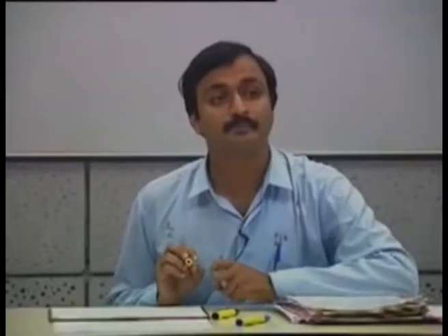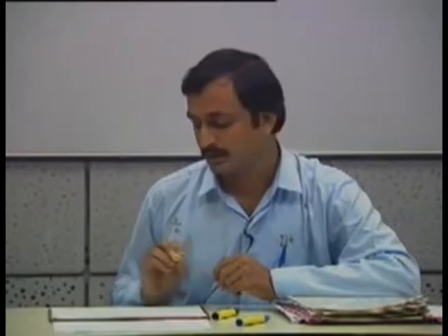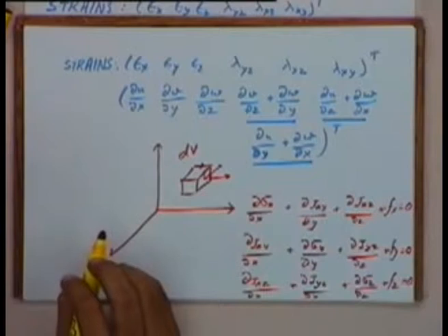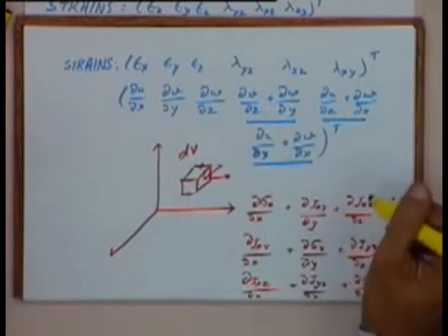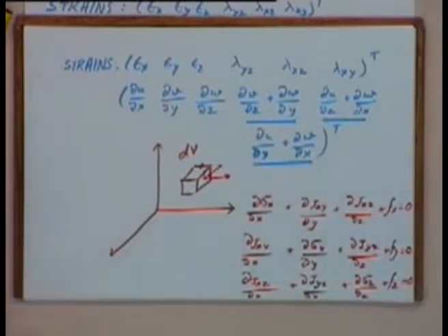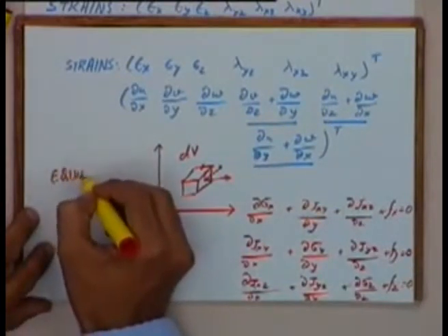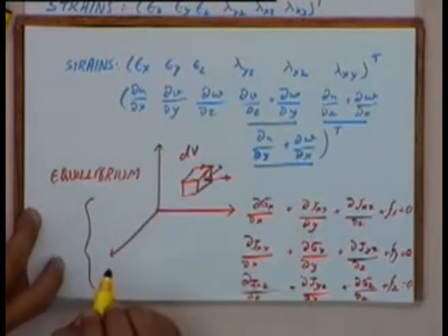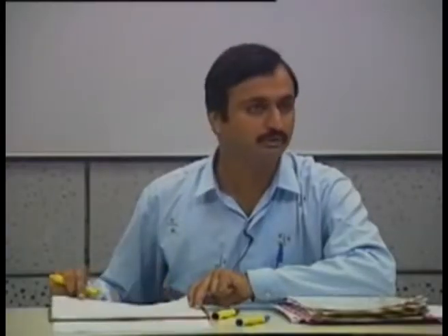Yeah. In all these equations, the force sign should be negative because the external force should be equal to the stresses. No, the signs will be taken care of by the direction that we are choosing. So the magnitude can be negative, but because of the sign convention we are choosing, we are getting a positive term. Okay, so there are 3 equations we get from equilibrium in an elemental body element, or in a cubical body element.